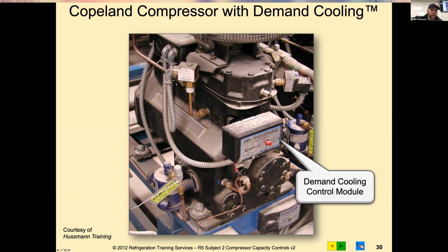Usually if you have to hit the red button, you're low on refrigerant, or for whatever reason, it's not cooling. This valve right here, if you guys can see my cursor, that solenoid is what is injecting that saturated vapor right below the head so that it mixes with the refrigerant here, immediately vaporizes into a low pressure vapor, but it gets us the volumes we need. It raises the pressure in the crankcase to get our compression ratio to a more tolerable state, fills that head with that cylinder wall with a good volume of refrigerant, and then rejects it out the discharge line.